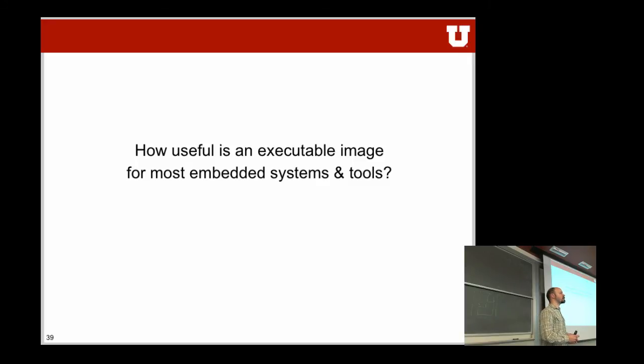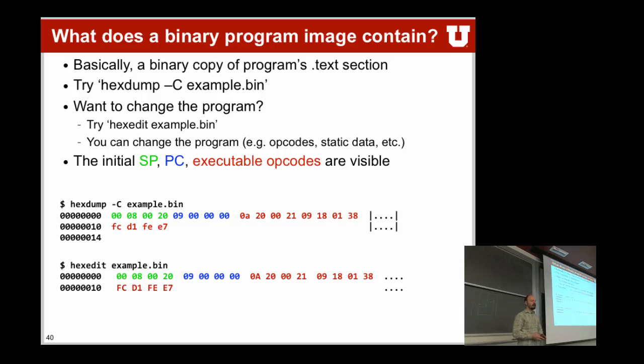Yes. These executable files are really important for debugging, because without them, you don't really know what's going on or what the different C instructions mean. So the executable file is really the link between your C code, your assembly code, your source files, and what's written in your binary file later on. So then, what does a binary file have in it? Once you send it through objdump, you can look at it again, and no big surprise really, right? We have the stack pointer, the first jump address, and after that comes your program. It's going to be sitting in code and gets executed as you tell the machine to do.